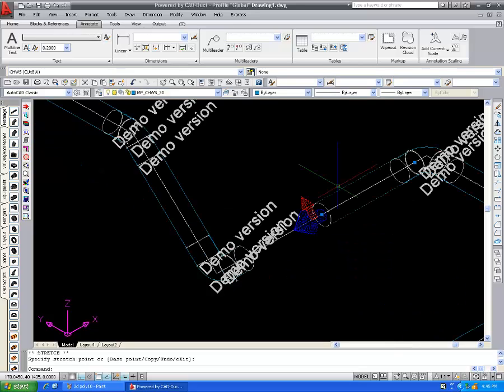I need to put a valve on this horizontal line. So we will grab the end of the pipe and stretch it backwards, opening up a space for the valve. It may help to have ortho enabled. Put the attacher on the pipe end. The attacher is on the tool icon menu on the left.